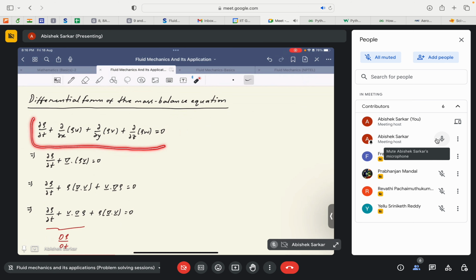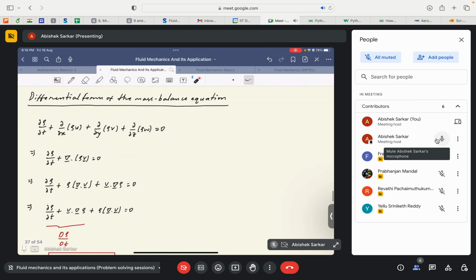How is this achieved? We apply the Gauss divergence theorem to the surface integral over the control surface in the mass conservation equation, and impose certain assumptions: a stationary control volume and a non-deformable control volume. Keeping those assumptions in mind, we can simplify our terms and find that the integrand becomes 0. Once the integrand becomes 0, this is the form of the mass conservation that we are left with. Okay, so you may wonder why I am not going through the derivation.